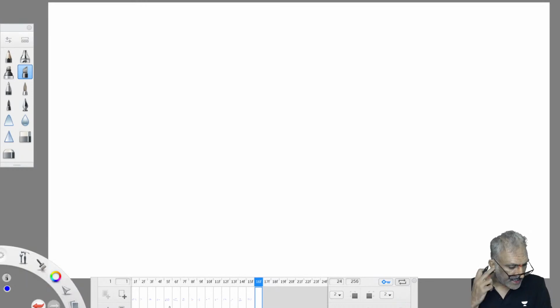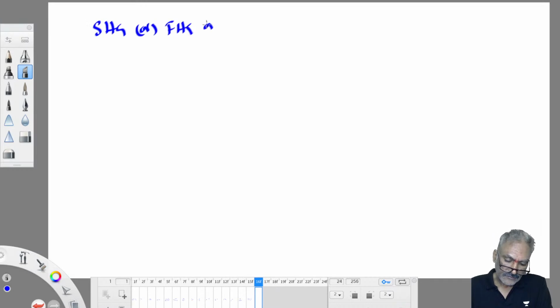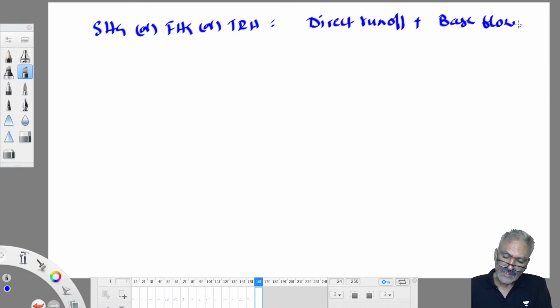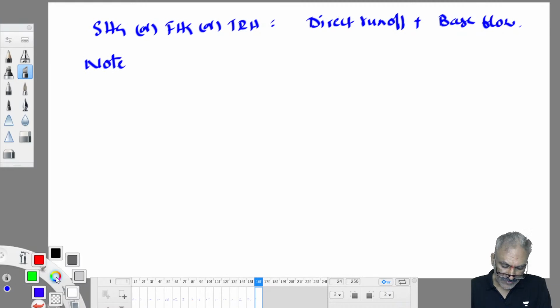But unfortunately the storm hydrograph or flood hydrograph, or total runoff hydrograph, consists of both direct runoff and base flow. But base flow we don't appreciate. It takes so long, we can't wait so long. Therefore, we separate base flow from direct runoff. Base flow is separated from direct runoff to obtain direct runoff from a catchment.